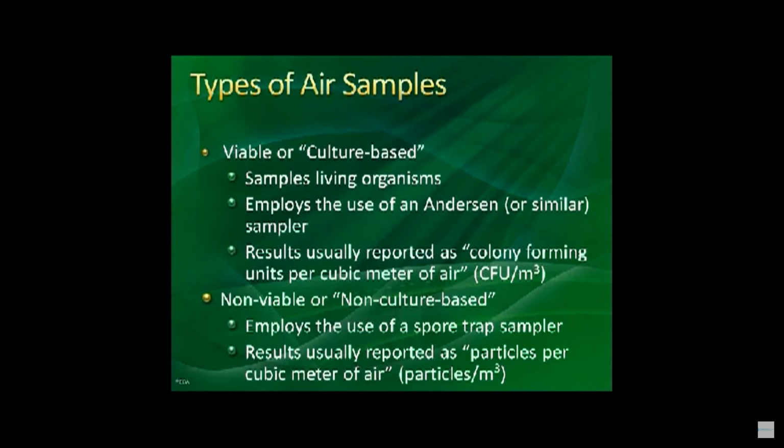In a simple base or your preliminaries, you do non-viable. This uses a spore trap. Very simple. You set it up for a certain amount of time, a certain amount of liters, and then the lab will report it to you in whatever the particles are per meter cubed of airspace. There's a long calculation they do, but they'll report it to you. What I always suggest as a start for those who are already doing or thinking about getting into viable is to do a non-viable test first to find out what is there in the air, to then determine what you're going to do for viables.